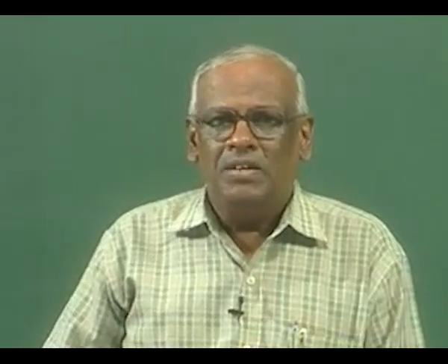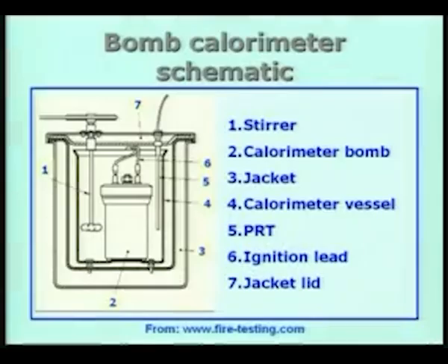the calorimeter. In the subsequent experiment, I am going to use whatever fuel I want to get the heating value of the fuel. I can use that fuel in the form of a pellet and repeat the experiment, and whatever C value I have determined in the first experiment, I am going to use as the C value for the second experiment, and therefore, I will obtain the unknown heating value in the second experiment. This is the basic idea.